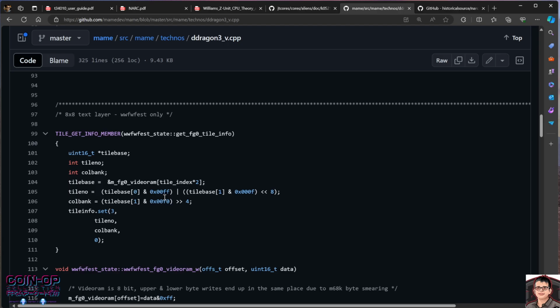And you're drawing to a line buffer, and then the line buffer gets flushed to the screen when the line counters go and it's in the active area, and it puts pixels on the screen, right? That's normally the procedure for an FPGA core, which is not all that dissimilar from how it was done on the real boards. Okay, some boards have a full frame buffer though.